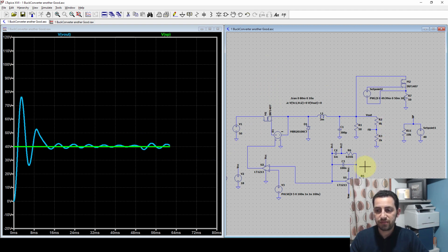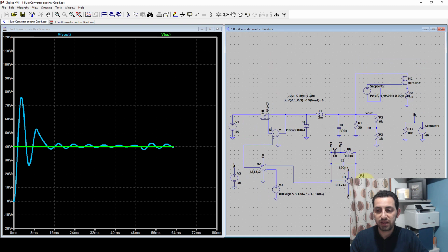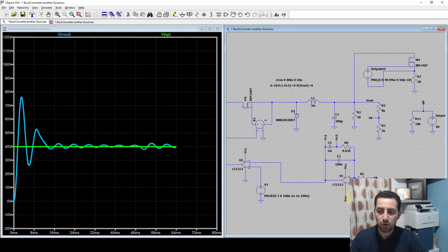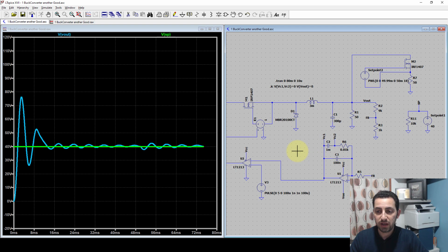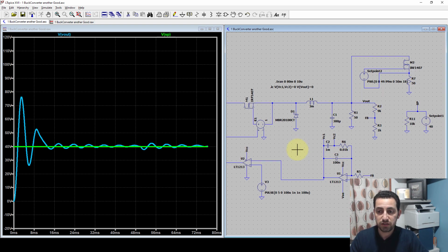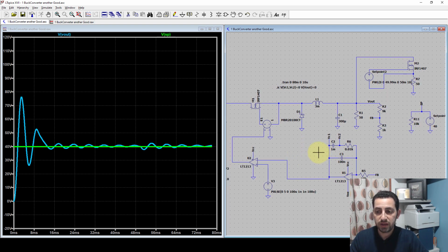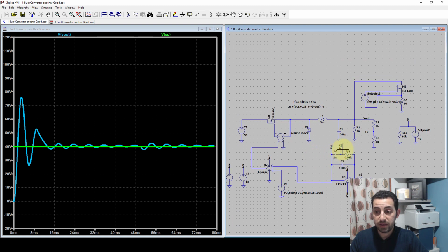So now this is the first network here, and if you look on the internet, what is this circuit called? There are three popular controllers. They are called type 1 compensator, type 2 compensator, and type 3 compensator. Okay, so this one is type 2 compensator. You can look on the internet and see what type 1, type 2, type 3 consider for a buck converter, and see how they select the values to enhance the response.